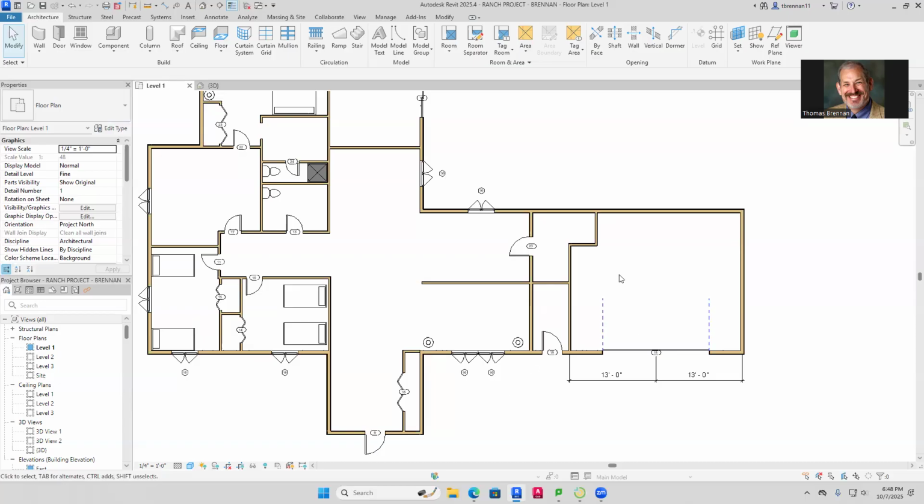Which items do we want to see, like insulation? You can put insulation in, sure. Essentially what we did, you could use the custom garage as a template. The detail we put in there, that's all we need to do. The custom garage had a single sole plate on the bottom, which is a single stud, and then the double top plate at the top. If you want to use that, you can. But essentially, if you just put in leaders which point out what the materials are, that's going to be plenty for me. Good question.